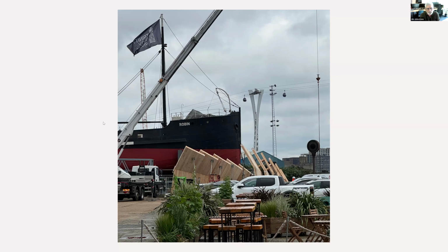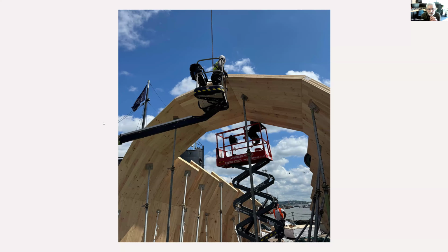Another shot of the same thing. Here we go. So we then, as I say, went a little bit off-piste, and rather than going all the way down with the third row, we realised that that was going to be quite heavy, and that would be relying purely on props holding it up. So we decided to complete each arch, and so work with the keystone effect of putting in the top one and locking the arch into position.